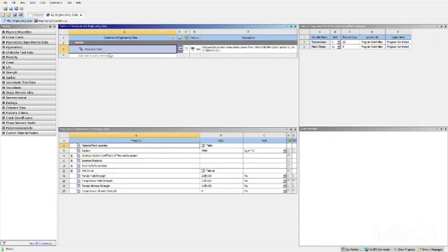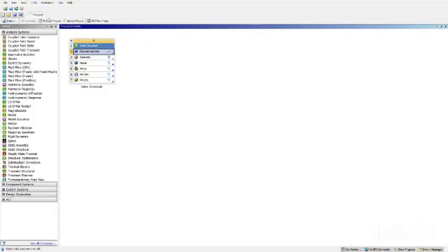and we will double click it, and here we will be shown different materials. By default there is structural steel. We can add different new materials in it. For that we will have to assign it properties like compressive strength, yield strength, and all the properties that will be needed. So we will continue with the default setting, that is structural steel. We will close this tab and again come to this. Now the next step is geometry.